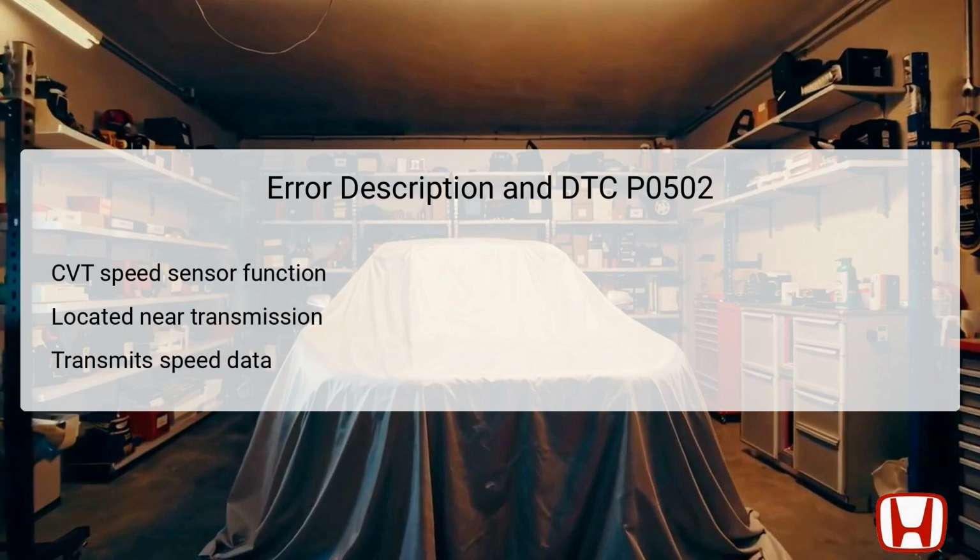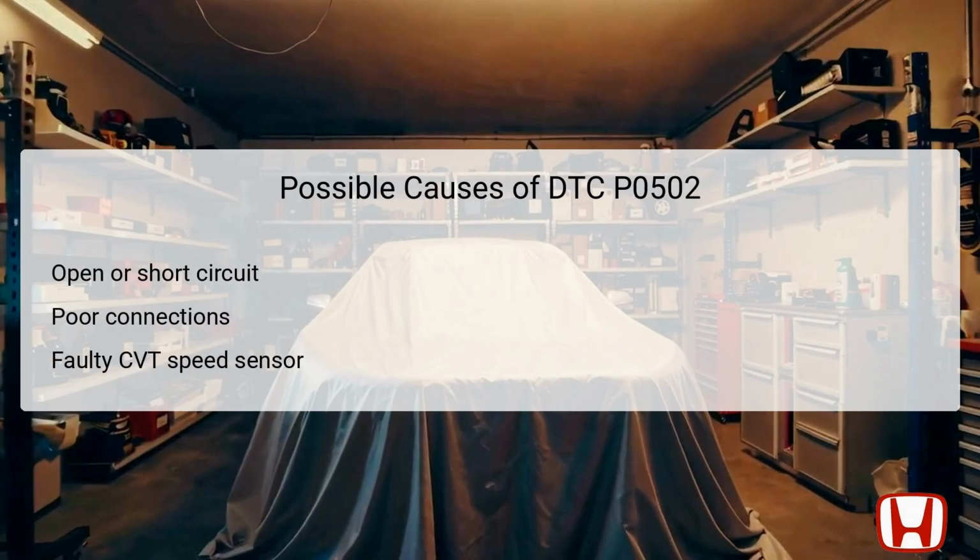Reviewing the Diagnostic Trouble Code, DTC, provides insight into the electrical issues affecting the sensor circuit, focusing on connectivity and voltage supply. Several issues could lead to DTC P0502 being triggered. First, an open or short circuit in the wiring can interrupt the signal from the CVT speed sensor to the TCM. These electrical failures can stem from frayed wires, corrosion, or loose connections.